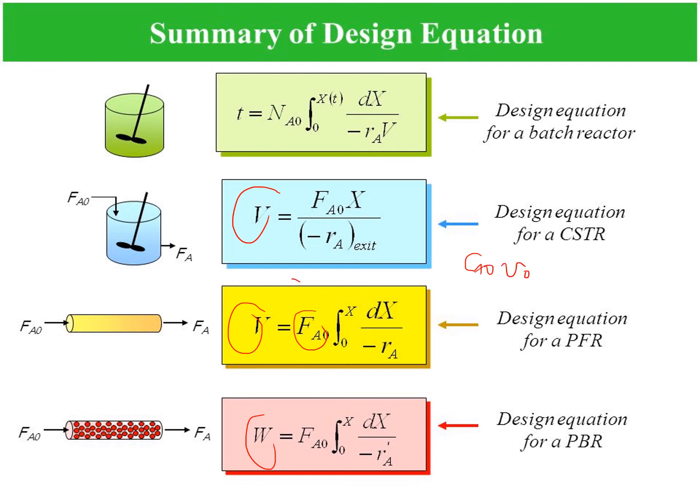So if we have CA0 over V0, we can relate V0 with V, because V is the volume, and we divide by V0. This one is the volumetric flow rate. This is in decimeter cube, and this one is decimeter cube over second. So you will get the time in seconds. Do you understand? This will apply to the next topic.